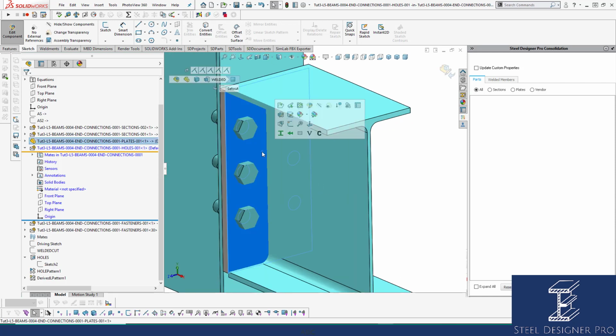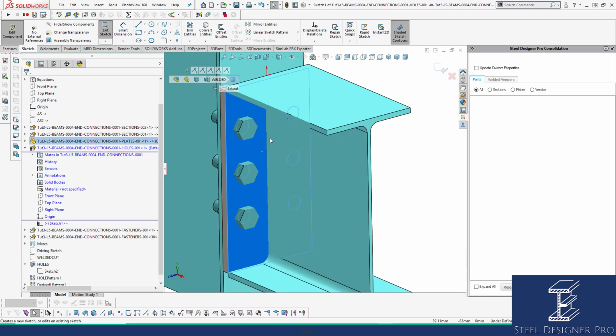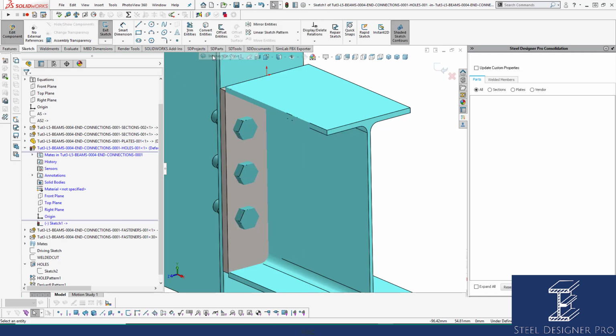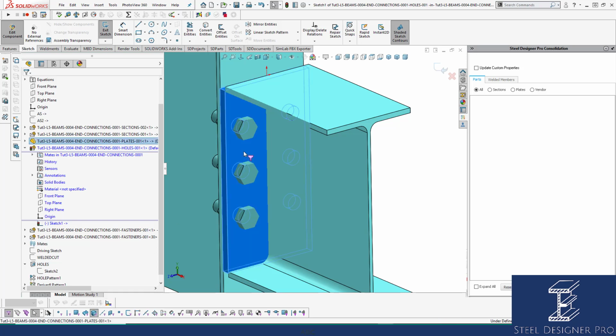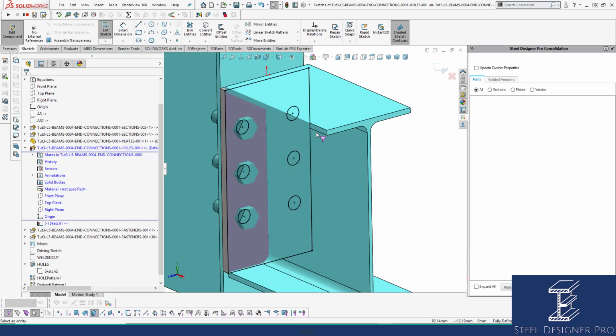So what we do is we start a sketch on this face. We then under there go intersection curve. Now before you go intersection curve, we need to select the body that we're going to intersect because it's on that face. So you know that that's the face that's going to be intersected curved. Okay, so we've selected the part. We then go into intersection curve. I don't know why my intersection curve is not coming up. Oh, there it is, it's done it.